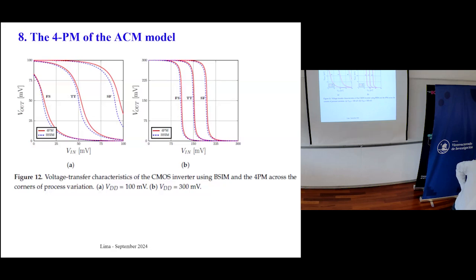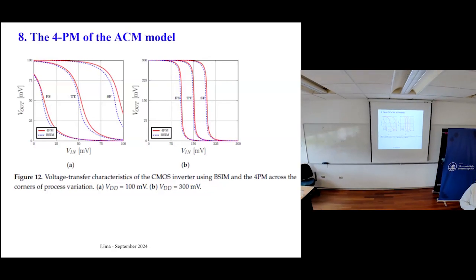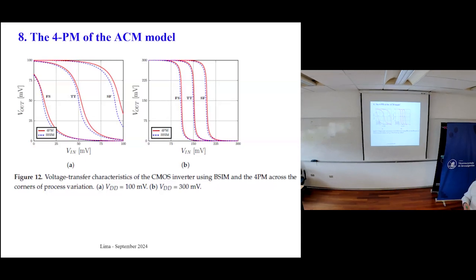We used integrated transistors, but off-the-shelf inductors, because inductors in integrated circuits are, I would say, poor. They have a very low quality factor. An ideal inductor has an infinite quality factor. It doesn't have losses, but this is very difficult to obtain.